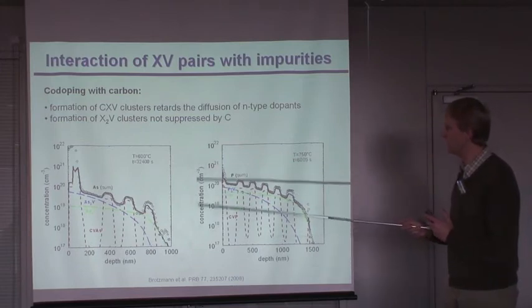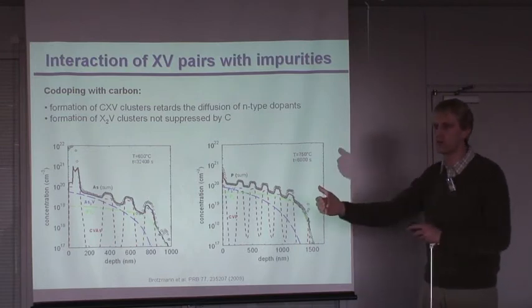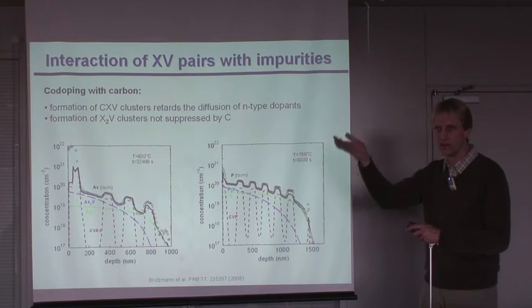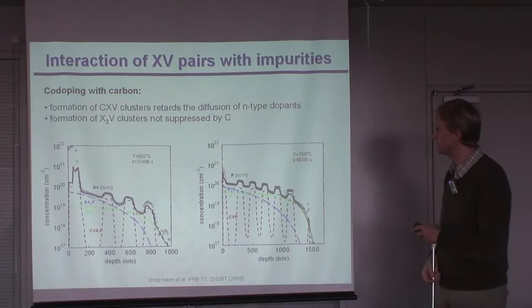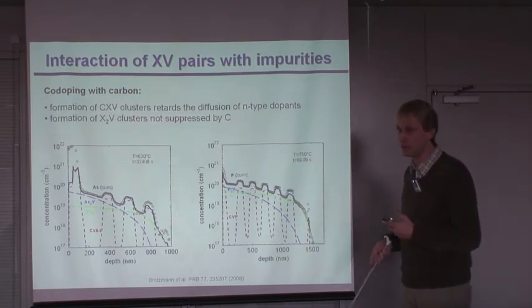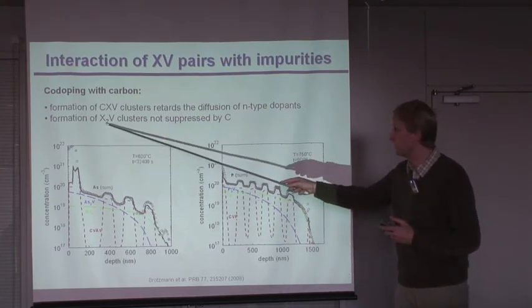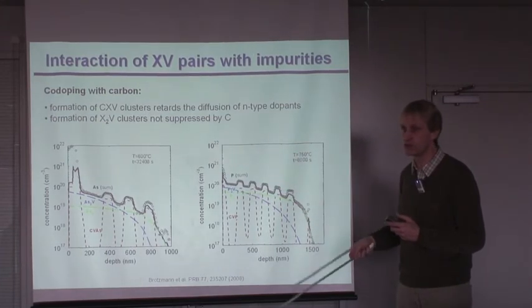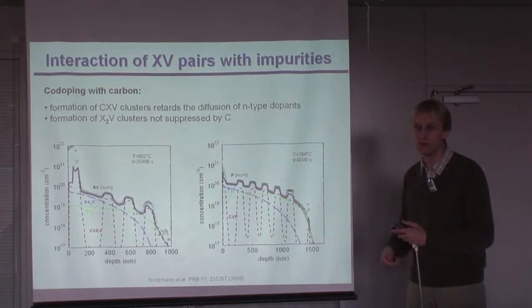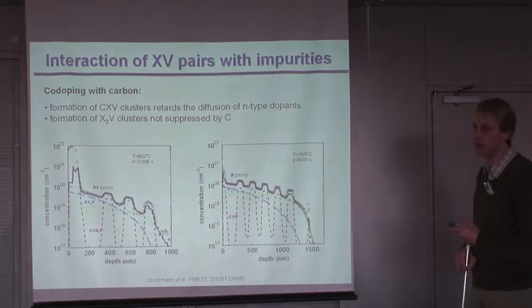And in the case of germanium with n-type dopants, under these conditions you end up with a huge diffusion of the n-type dopants due to the high diffusivity under extrinsic doping conditions, and this you can avoid a little bit by co-doping with carbon. But unfortunately, the deactivation, this neutral cluster formation which also takes place, cannot be suppressed with carbon. So that would not be the solution in order to realize an N-channel MOSFET just based on germanium.